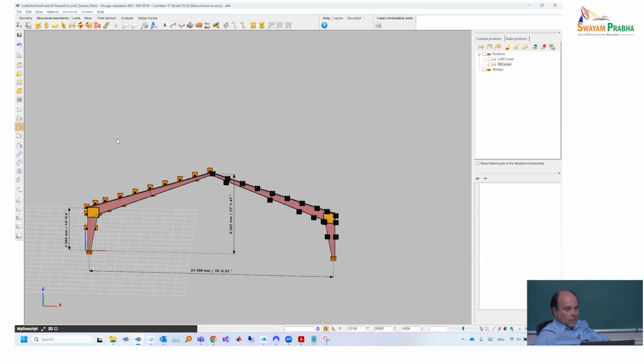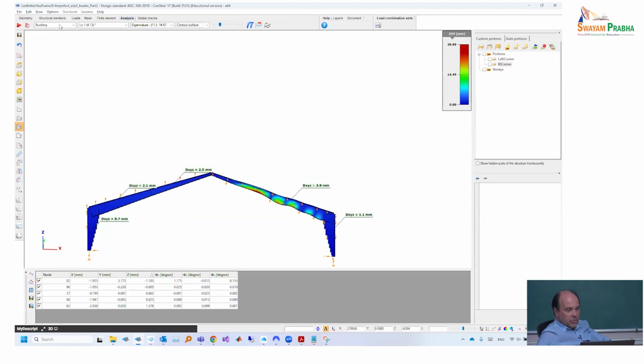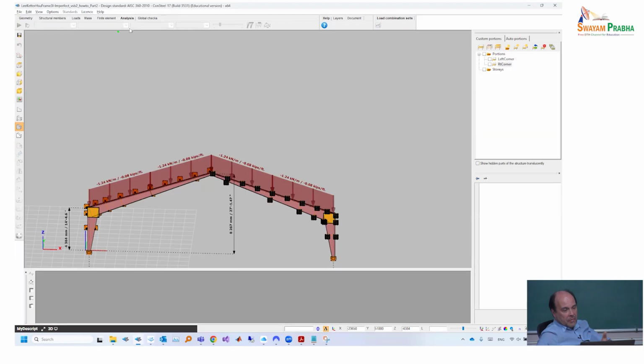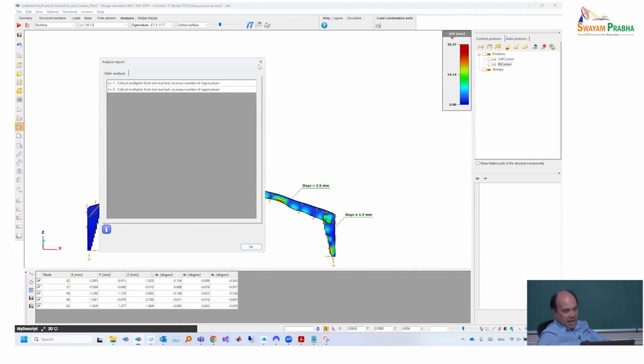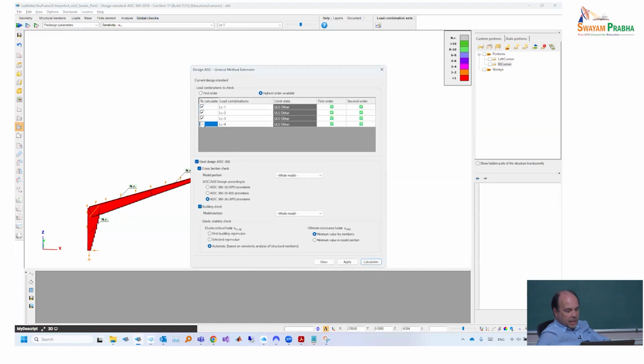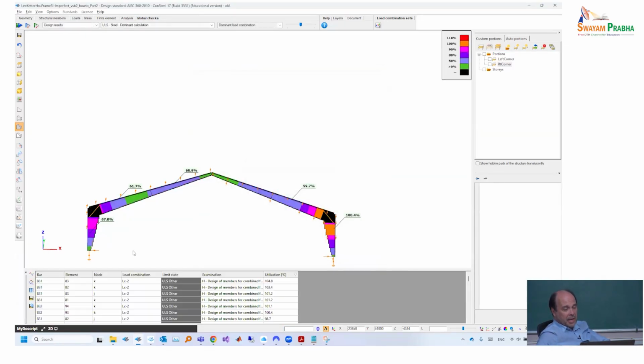Okay, so now when I do nothing more, I just run the calculation, and now this addition will be considered. I still have this message which I explained to you what it means. And now again I select all the other combinations together. I select the automatic, which is already the effect of the buckling sensitivity calculation, and run the calculation again. And the results did not change at all up to now, because again, on the column at least, it's still the web local buckling that is relevant.